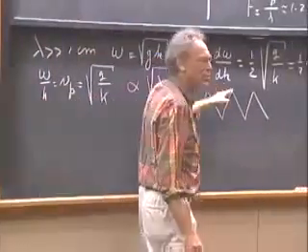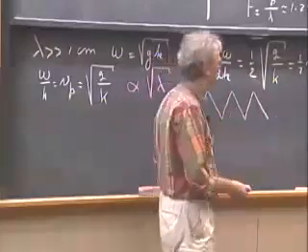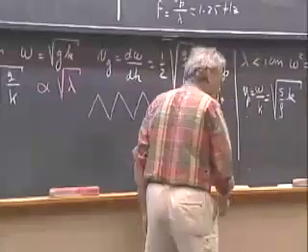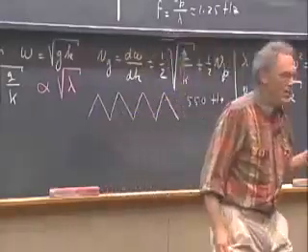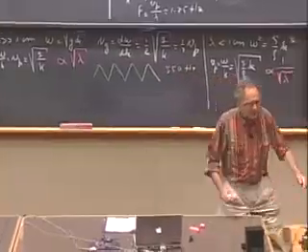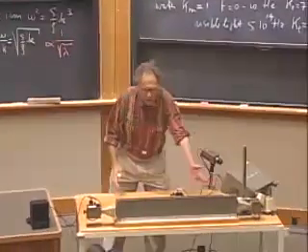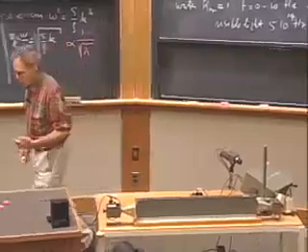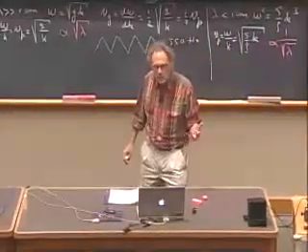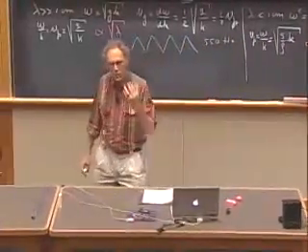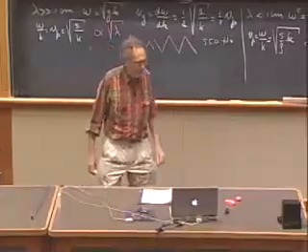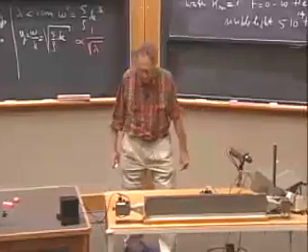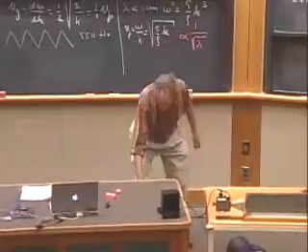If this were a nice sinusoid, you would hear a beautiful 550 hertz tone, but because we modulate it with a triangle, it's a nasty tone. The only reason we want you to hear something is that when this receiver receives the radar signal, we want to hear this modulated signal. Unfortunately, you and I cannot hear 10 gigahertz. Our ears are not designed to follow a frequency of 10 billion hertz. It cuts off at 20 kilohertz, as you remember. So, we're going to show you this